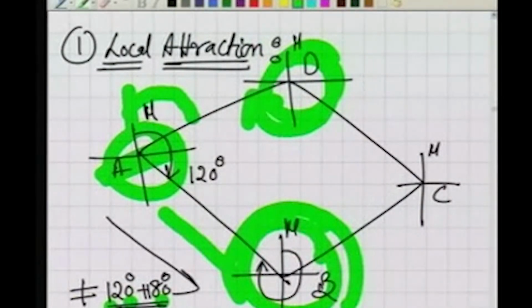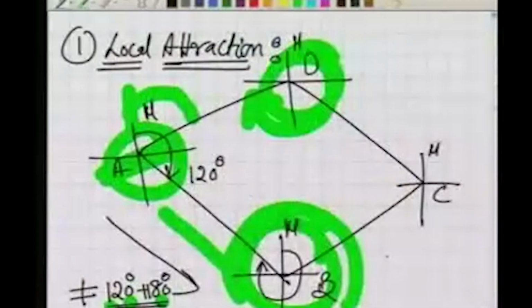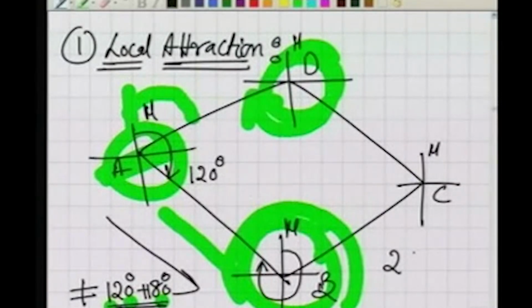So what we can do, if for example the value observed at B was 290, let us say. Just for example, we are taking that the value observed at point B, the back bearing of line AB was 290. So we will apply some correction to this because we know that discrepancy.